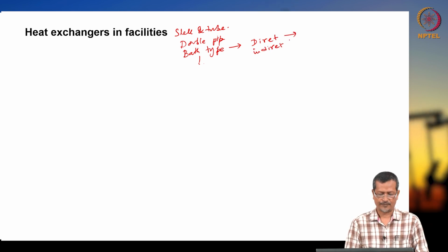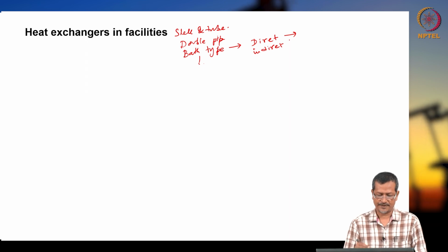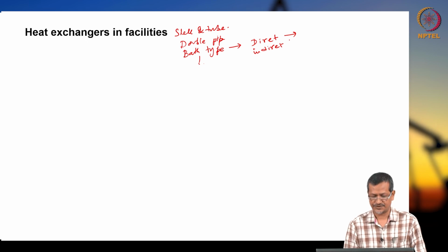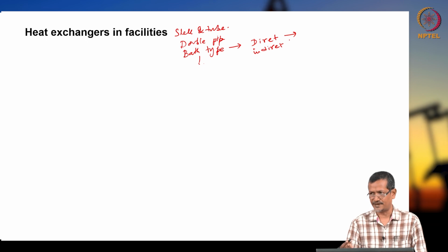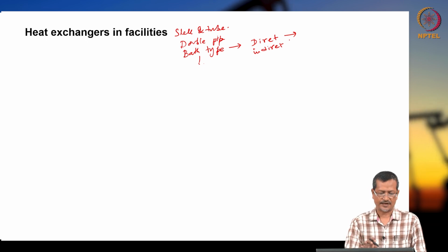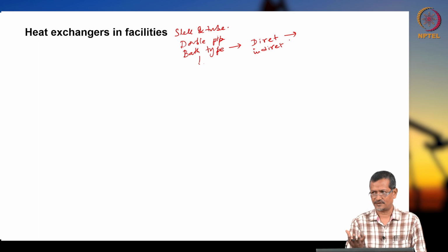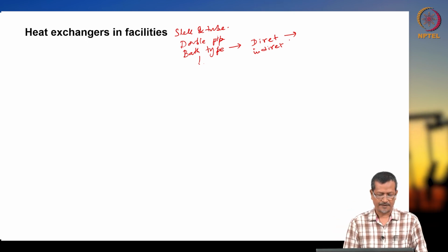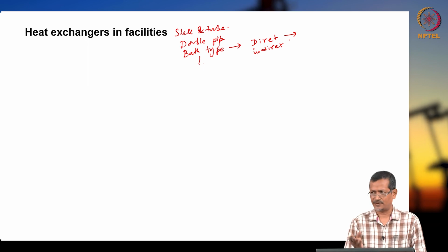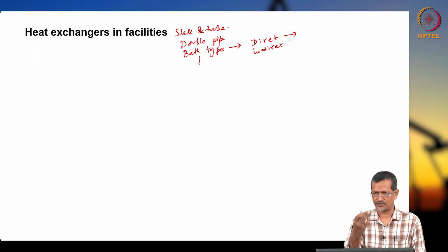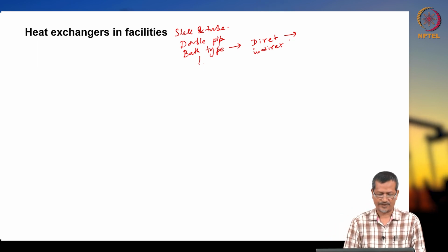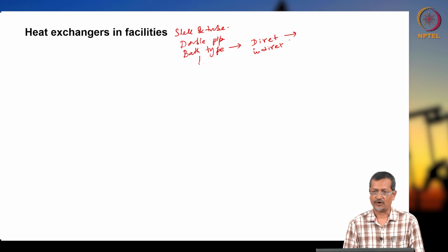In the direct type, the heat source for a bath heater can be a coil of a hot medium such as steam, waste heat, or exhaust from an engine or turbine. That heat can be used in a direct heating system. So you have hot gas and you are directly heating oil or whatever you want to heat. For example, an immersion heater, normally you may have used one, right? You immerse it directly, so the heating coil transfers heat to your water. So heat is transferred directly to the oil bath.